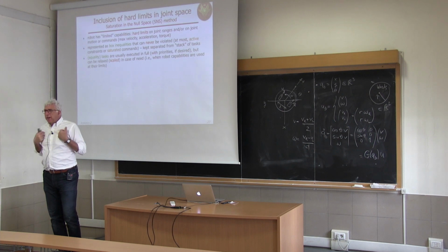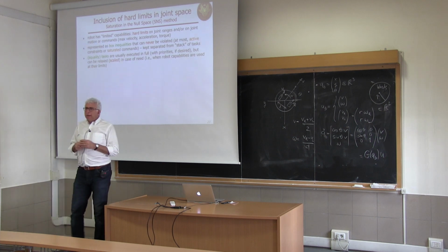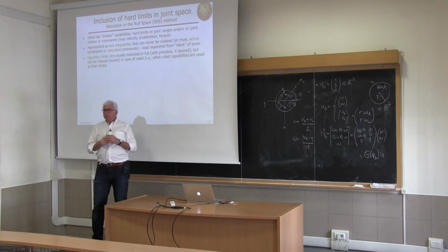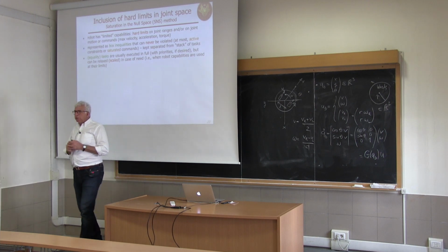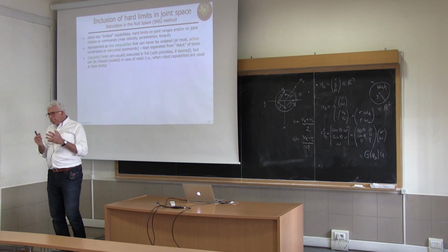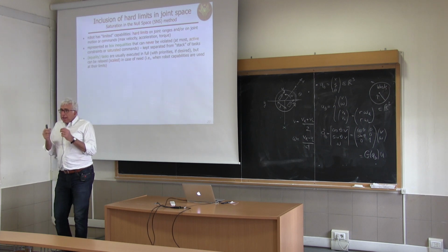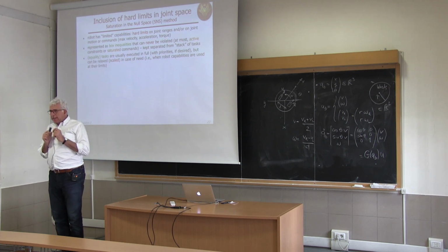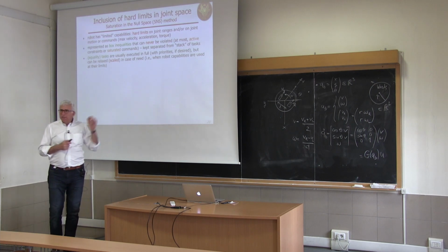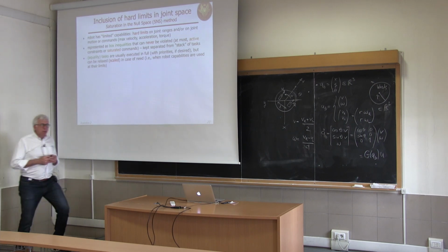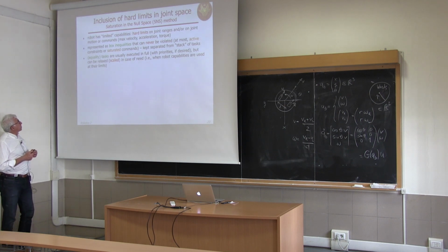And if this violates the hard constraint, there's nothing to do. I mean, we would not like to execute the task minimizing the geometric norm of the trajectory error. We would prefer to say, okay, let's scale down the speed of this task so that we do the same geometric path, so we go along the same direction at every configuration, but with a lower speed. So this is again a relaxation, but of a completely different type than the one that we have seen so far in the hierarchical quadratic programming framework.